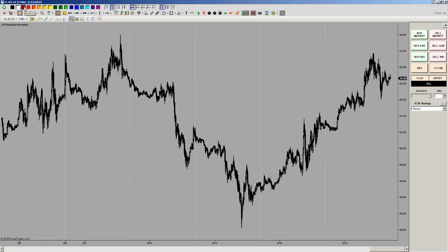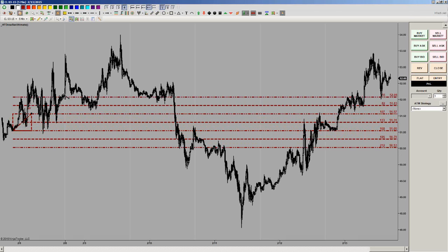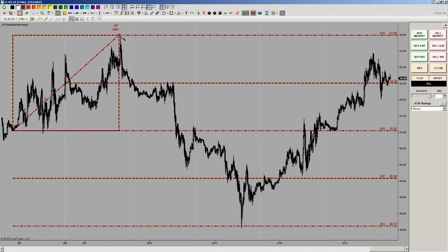I can choose a color, red. I can choose the line width, so let's say 4. This is our style: dash, dash-dot, dash-dot-dot. Let's do dash-dot-dot, 4, with a color of red. I pick my line and draw my line from there to there.